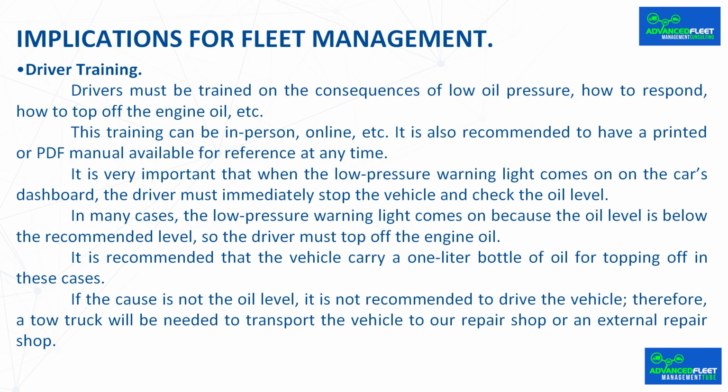Driver training. Drivers must be trained on the consequences of low oil pressure, how to respond, how to top off the engine oil, etc. This training can be in person, online, etc. It is also recommended to have a printed or PDF manual available for reference at any time. It is very important that when the low pressure warning light comes on the car's dashboard, the driver must immediately stop the vehicle and check the oil level.